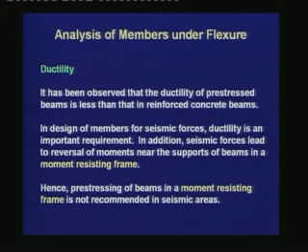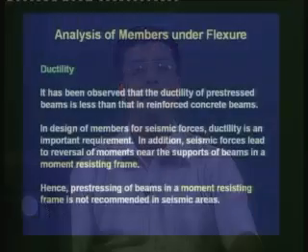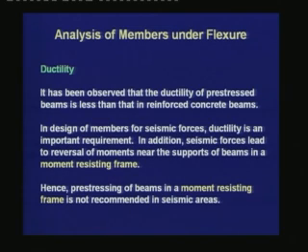That means there are two considerations why prestressing may not be helpful in a seismic region. First, the ductility of a prestressed member is lower than a reinforced concrete member. Second, there is a chance of reverse moment acting under seismic forces near the supports of the beams. Hence, prestressing is not recommended for beams in a moment resisting frame.